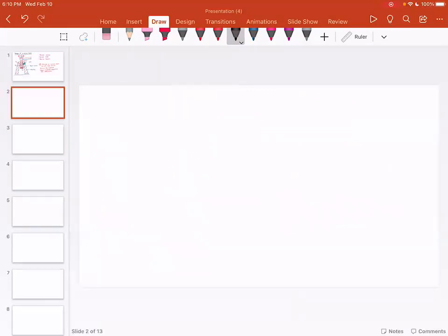Step one. In step one, we will find the core diameter of the nut. And if you look at the core diameter of the nut, failure is in pure compression. Now, please understand that this nut is held in place by a support at the bottom and is loaded on the top. So this load is purely compressive. So step one, determination of core diameter.